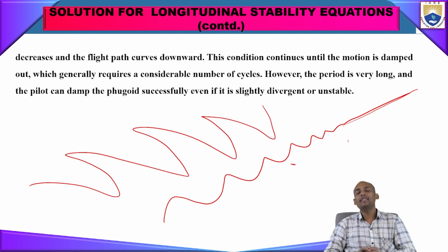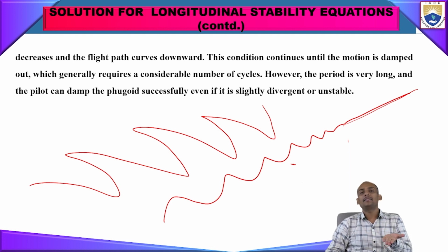So with this, what we are saying is, in a linear equation of motion we are getting the changes in alpha, theta and momentum with respect to the flight data values. When we give the flight data values, we get the stability derivative values. After that, from the stability derivatives, we get the frequency response of the total aircraft, with the short period oscillation and the phugoid oscillation. So a small change at that speed gives this much change in damping.